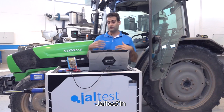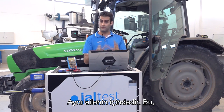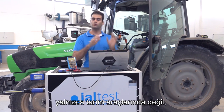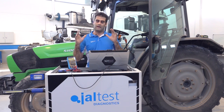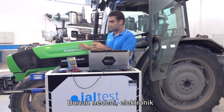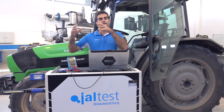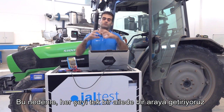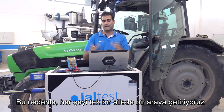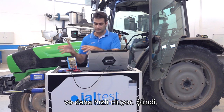Don't freak out if you find that Jaltest does not have the specific model. It's inside one family. It happens quite often, not only in agricultural vehicles, also in construction machinery. It's because most of the electronic control units are the same within the same family of vehicles. So we put everything together in one family, and therefore it's easier. At the very beginning it can be a little bit confusing, but in the end it's easier and faster.